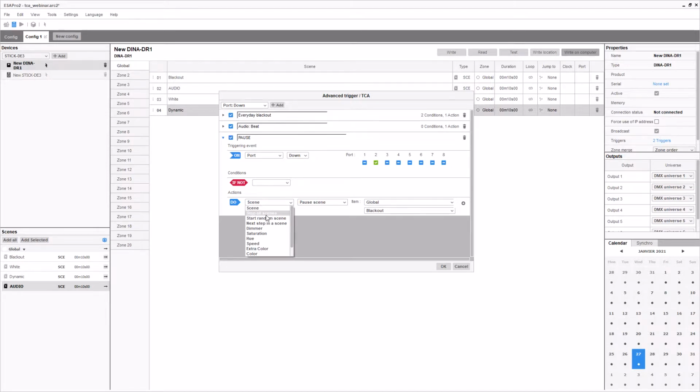You can stop all scenes, which means this is a blackout button as well. You can add a button somewhere in the building, just a push button, and this is the button to turn the lights off. No problem with that. You can do blackout. You see, black off or toggle as well. Different ways to do it. You can call a blackout scene, blackout the controller, which means release every scene, or stop all scenes. Again, it will depend on the situation, and sometimes we have offered all those possibilities.